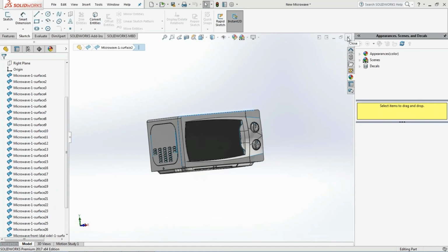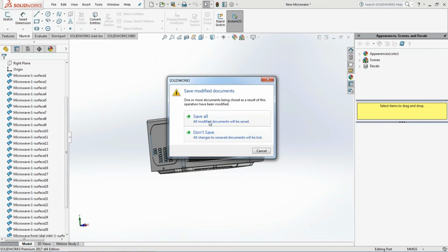A point source would most likely generate all kinds of modes, and then you would just calculate the radiated power if you treated your structure as an antenna, and see how much of that power is actually leaking out. In that case, you're not really worried about any kind of mode in the structure. All the modes are going to be taken into account.